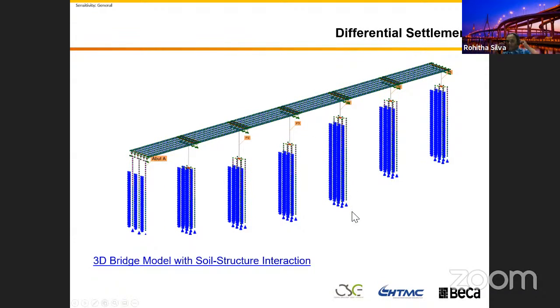If you're designing a continuous span bridge, the differential settlement analysis is quite important, because if this particular bridge pier settles by more than 20 mm compared to the other two, that generates significant bending and forces in your spans because of the continuity in the bridge deck, superstructure and substructure. It all depends on the type of bridge, how we're going to employ them.